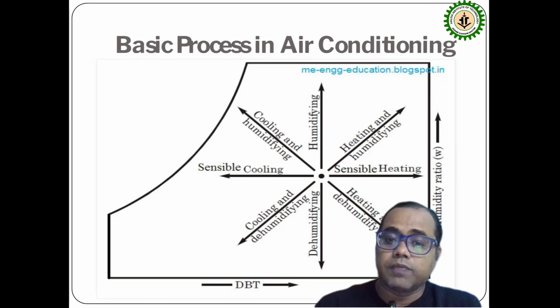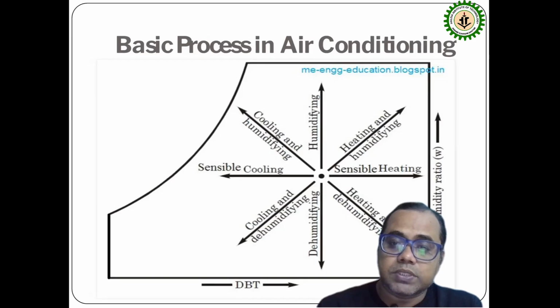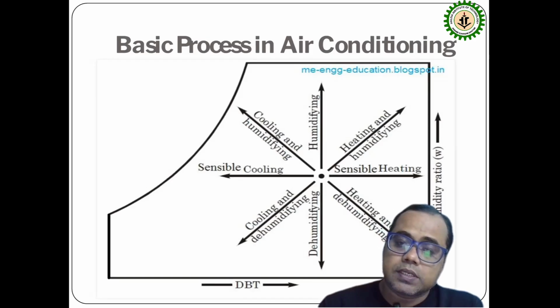Okay. If you know the process, it will follow this direction. In this way, all these parameters you can calculate very rapidly, which will be used for calculation purposes. Suppose different specific volume, air enthalpy, humidity, relative humidity, humidity ratio. By this, we can calculate the capacity of the cold storage. Okay. So next class, I will discuss how we will calculate the capacity of the cold storage by these processes.